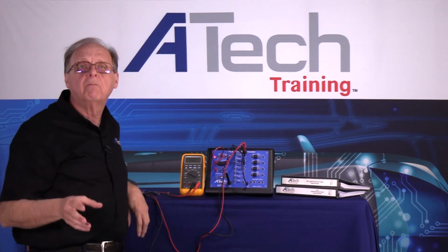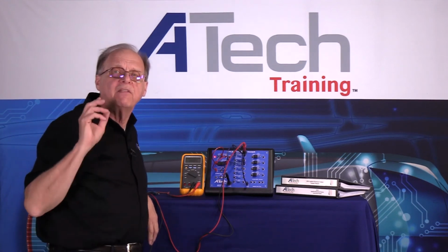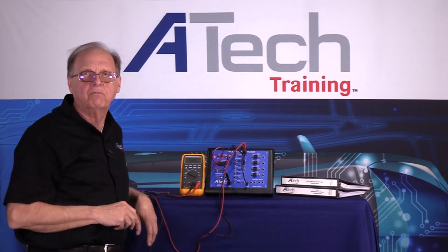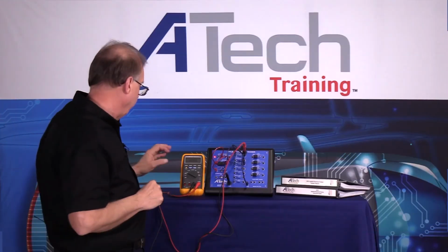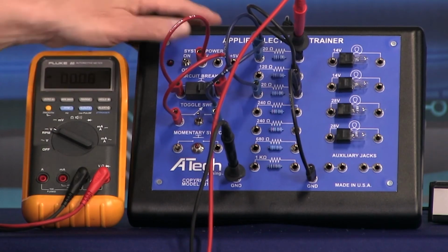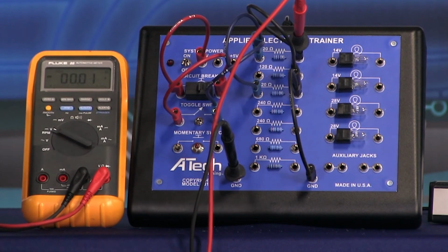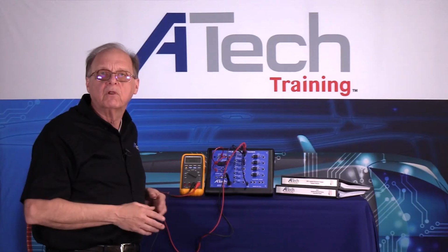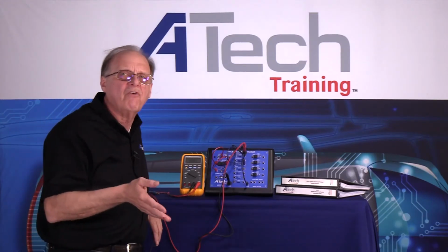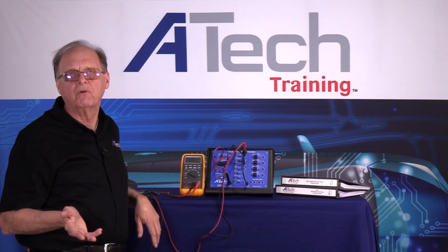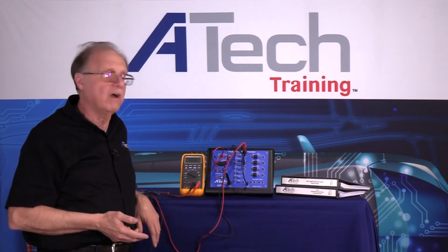You have to be able to teach them to use resistance and not always make sure you have to have a light bulb to do the testing. If I'm doing resistance, I'm going to turn the circuit off. No power. If we're doing resistance, the circuit should be what? Off, not working. Because I don't want any voltage running across it. Your voltmeter will put out a slight bit of voltage, like 0.6 volts when it's doing an ohm test. A little higher when you're doing a diode test.